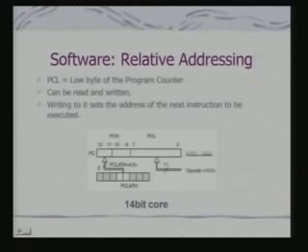The offset is an 11-bit offset which is part of the instruction. So, all your goto and call operations are PC relative. This is the key significance of the most significant bits coming from the PC latch high register.